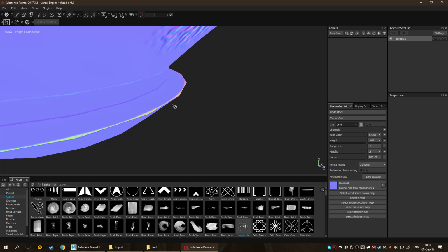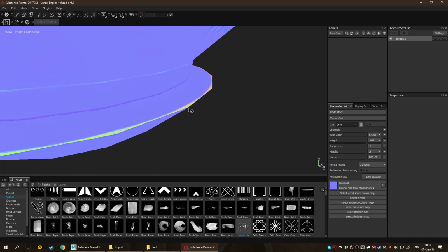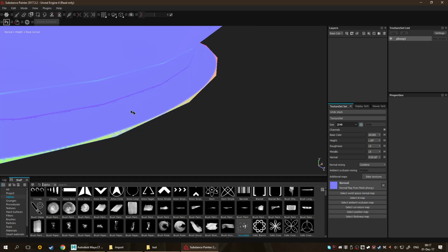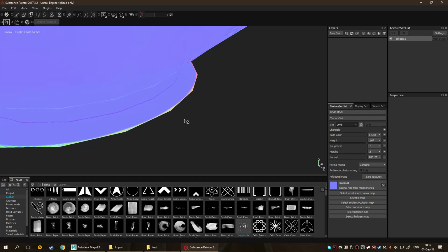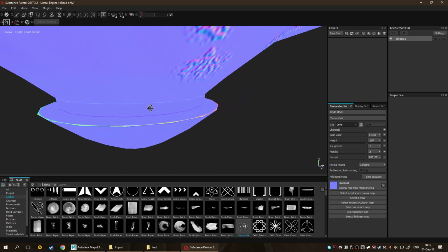And obviously, as you keep increasing the subdivisions on it, yeah, you'll be regaining some of that volume, but at the end of the day, you're still losing it. So whenever you're doing this kind of stuff, you want to have your low poly approximately close to your initial form, right? You don't want to have something ridiculously huge like this. In most cases, you could get away with having a little bit bigger high poly than low poly, but having a bigger low poly than high poly will almost always cause an issue when it comes to your map generation.